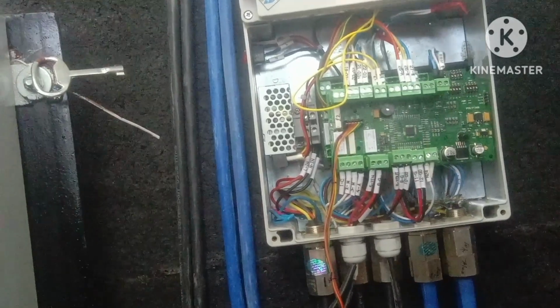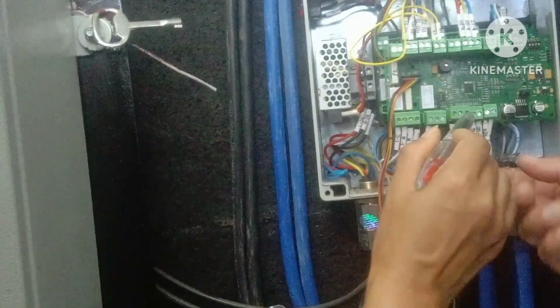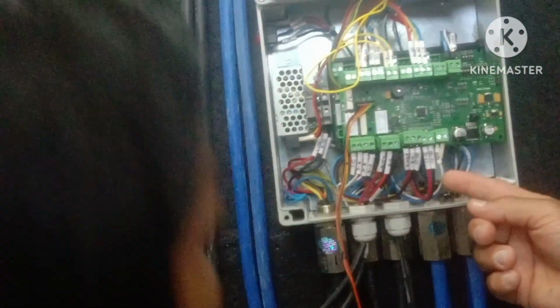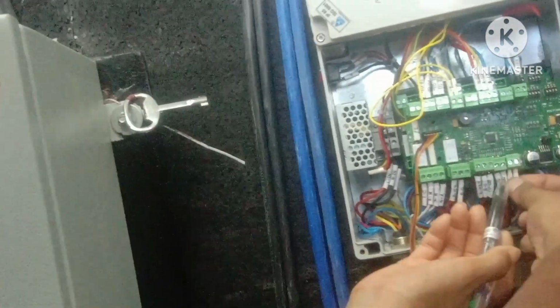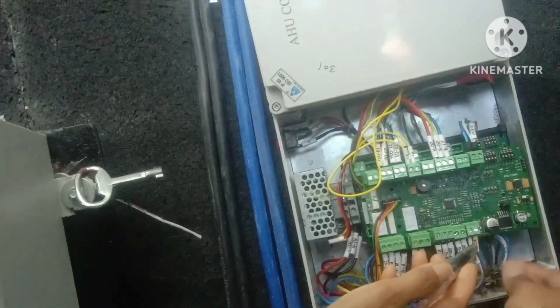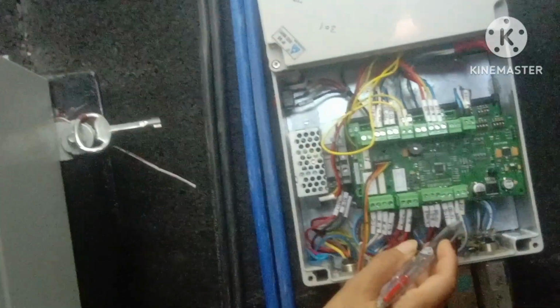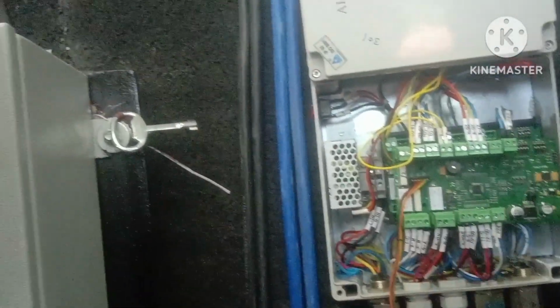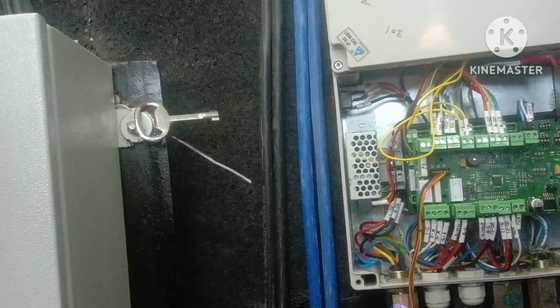Yeah, see, it's written positive P24 and 24. Okay, so the positive should be connected to the last point and the negative terminal should be connected to the second last point. Here you will be able to see 24 volt DC. I am repeating, the actuator is operating on 24 volt AC and the PCB is operating on 24 volt